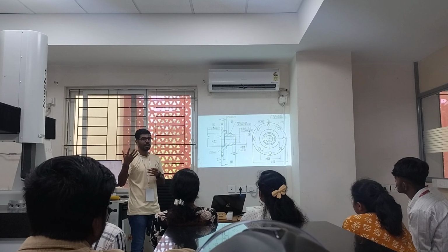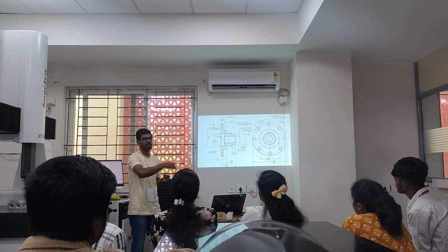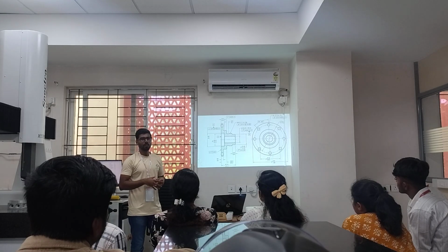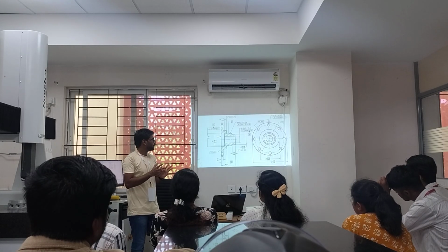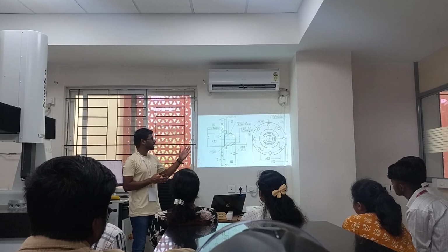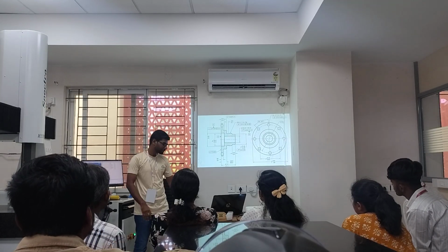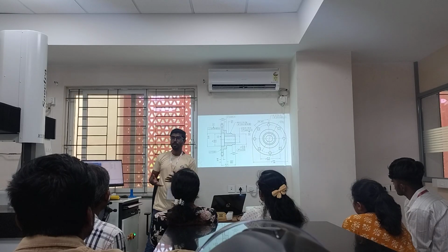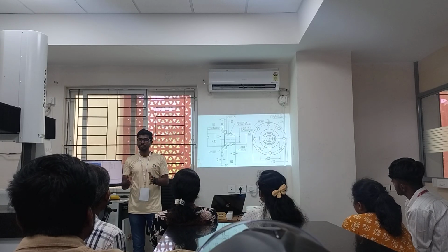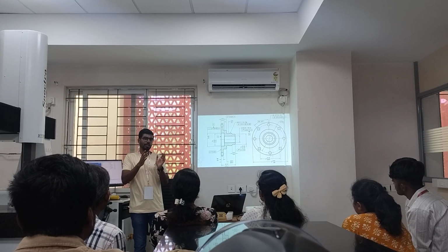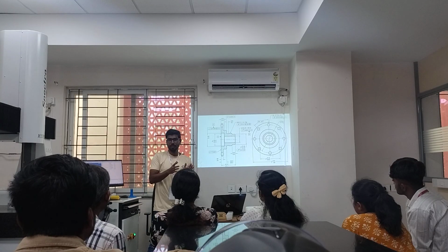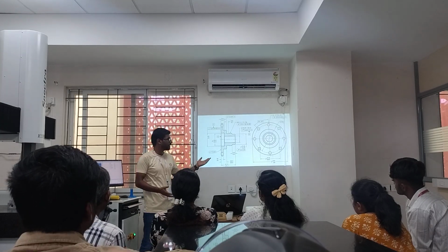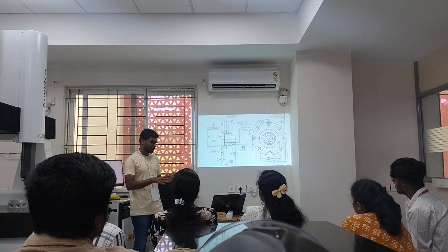If you are a design engineer and want to convey something to the production engineer or a manufacturing engineer, how will you convey? It will only be done through drawings, and in drawings you have to follow the GD&T rules. Using these drawings, a person in quality has to make sure that the part is under conformance. If it is non-conformance, if it deviates from the drawings, the person in quality checking will just reject it.